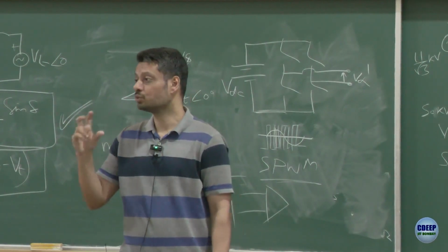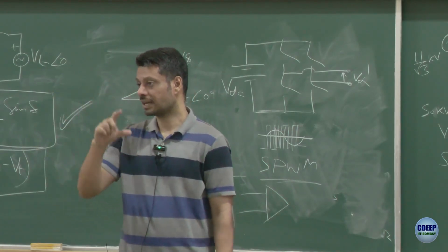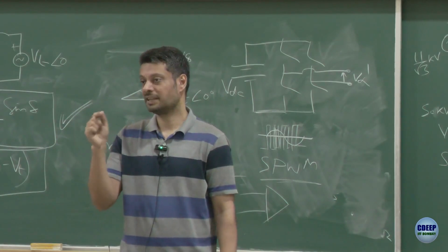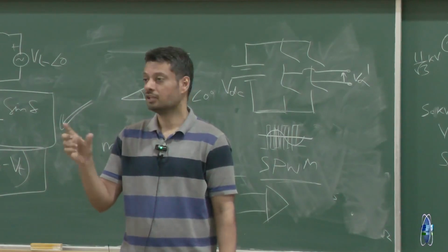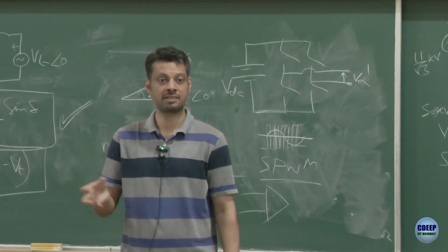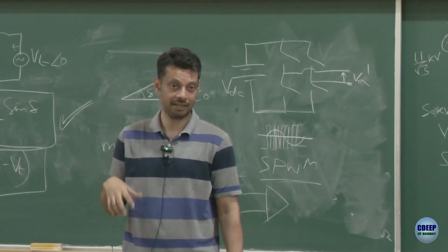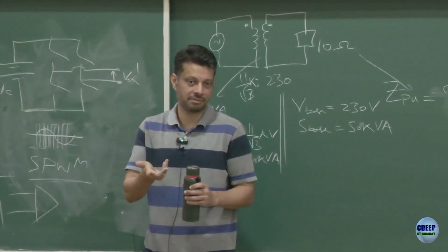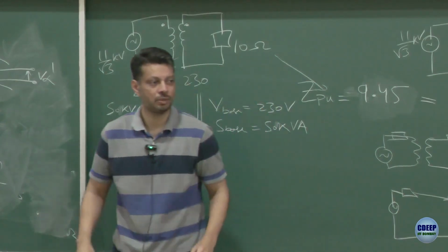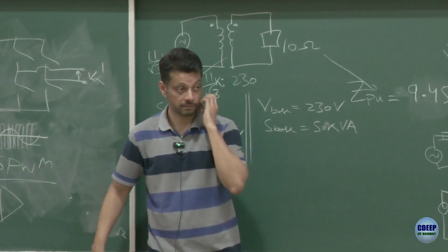Together they can offer you controllable inductance and capacitance. This class is called FACTS, Flexible AC Transmission Systems. If you search for flexible AC transmission system devices, you would see a host of devices which can do a lot more things. Later on, if you want, you can do a course in FACTS to learn more. It's possible now, but it's expensive nevertheless. So initially power is 0, but once you are connected, you can change the delta and flow the power you want.